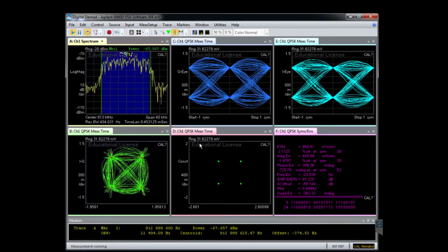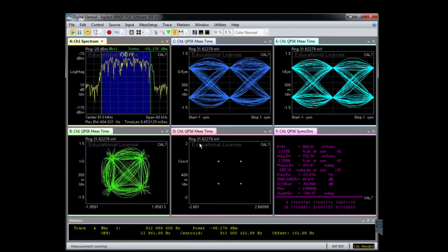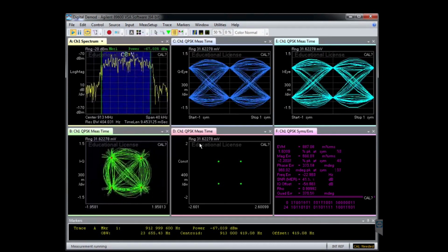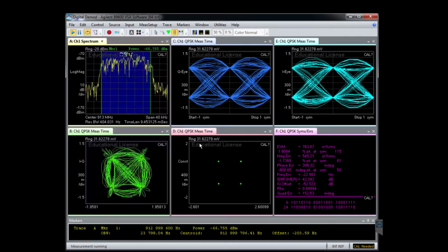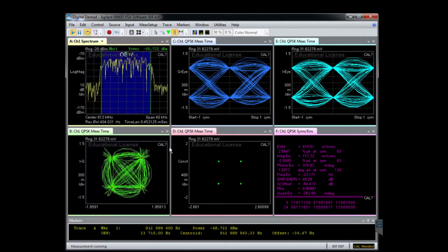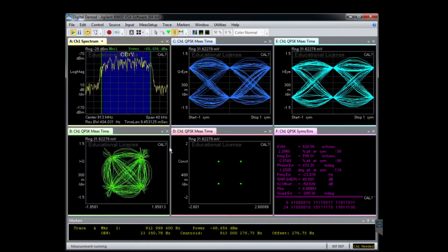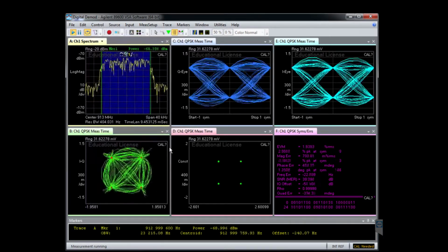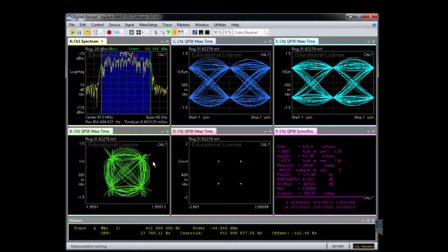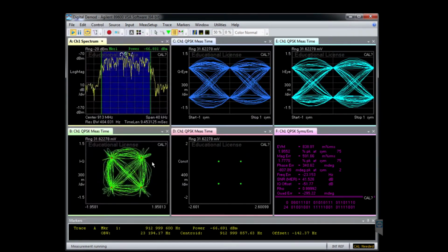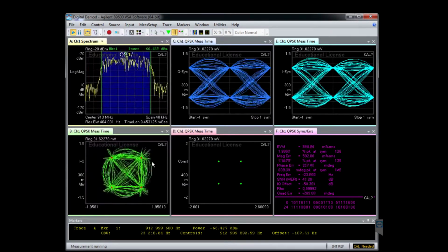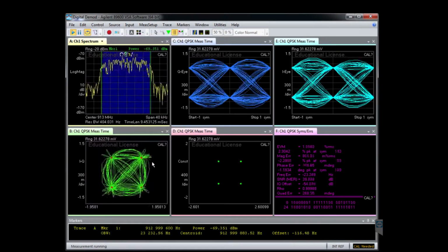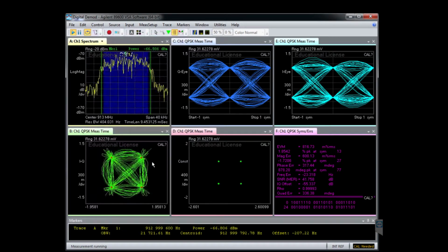So you will observe, when you are performing this in the lab, you will keep increasing the signal up to minus 20 dBm in steps of 10 as specified in your manual. At the end, you are required to estimate the SNR from the spectrum and also calculate the SNR from the EVM. We have already shown you how to estimate the SNR from the spectrum in the previous lab. And also in the lecture, you have been shown the formula that relates the SNR and EVM, so you have to use that formula also.